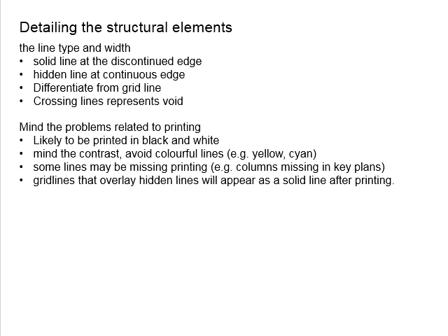As for the students, normally students are not required to print in A1, but there are chances that the drawings are printed in A3 papers. You have to be careful with the scale. It would be good if you indicate the scale when the technical drawing is to be printed in A1, and also use some simple calculations to calculate the printed scale when it is in A3. And if you want to confirm whether your calculation is correct, print one page in A3 and then use the rulers to measure in order to cross-check the ratios.